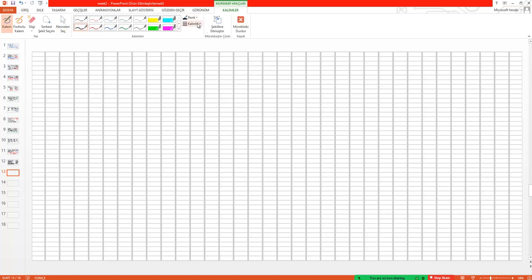The second equation is coming from the mechanical analogy. Secondly, the mechanical equations can be given as follows. We have the torque value produced from the rotor and stator, okay? And this is consumed with the theta m double dot times Jm. This is the inertia or energy-preserving element of this form.